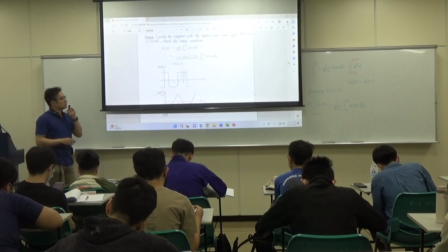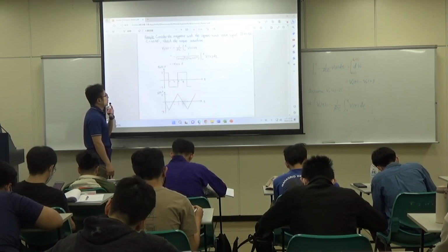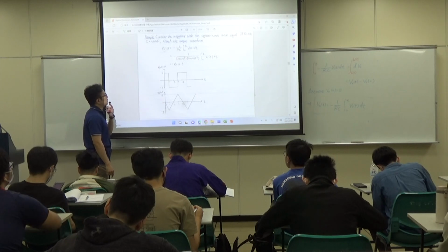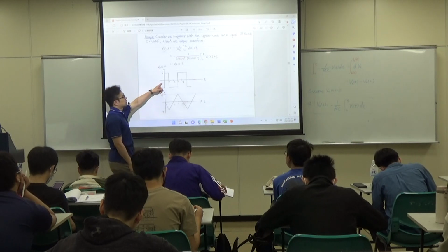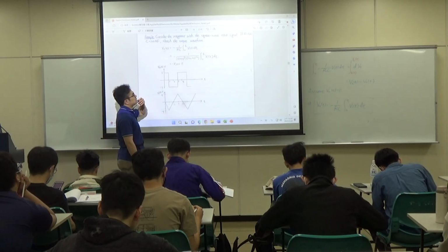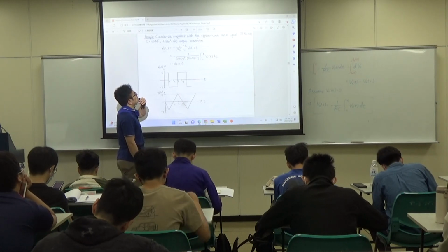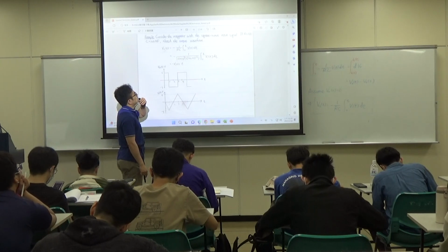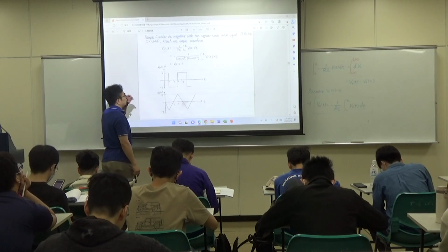Okay, what does this say? It says consider the integrator with the square wave. This is called a square wave input signal. If R equals 10k ohm and C is 100 μF, sketch the output waveform.